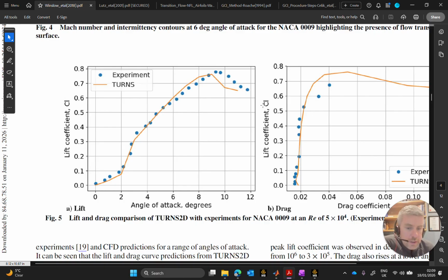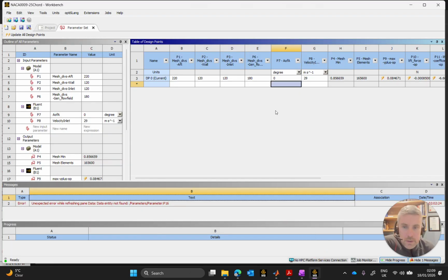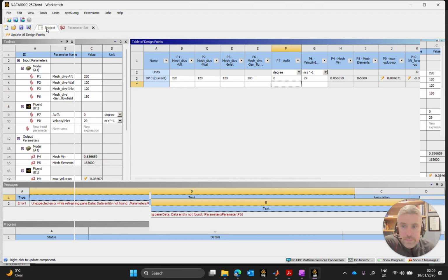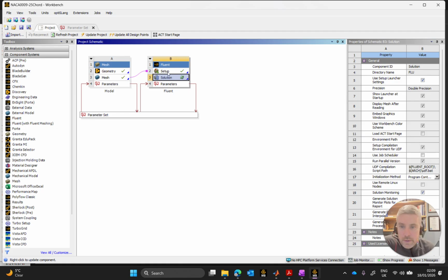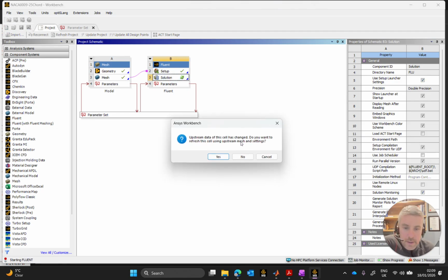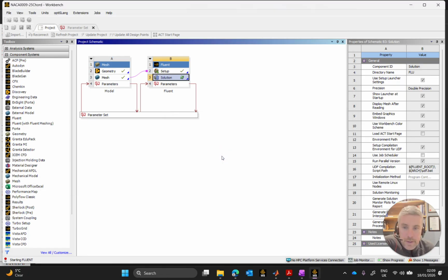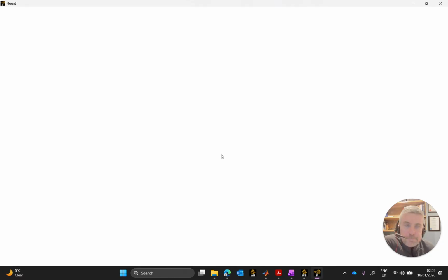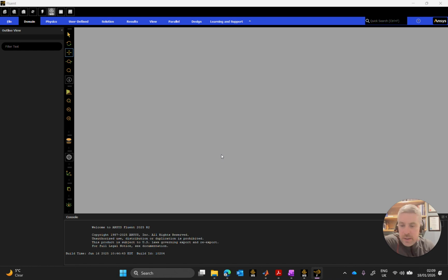If they're all thereabouts, we know we're on to something here. We're on to the winner. So what I'm going to do is go back into solution, and I want to check to make sure that my pressure coefficient is reading the minimum facet data as opposed to the maximum facet data.